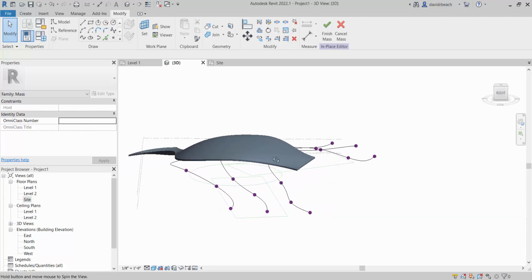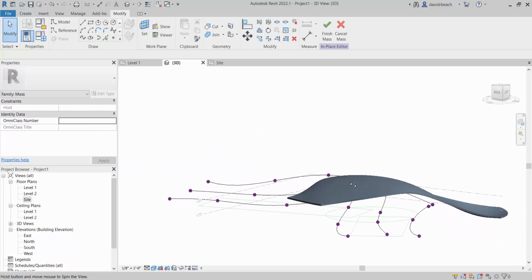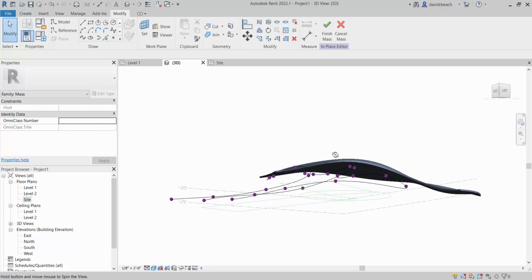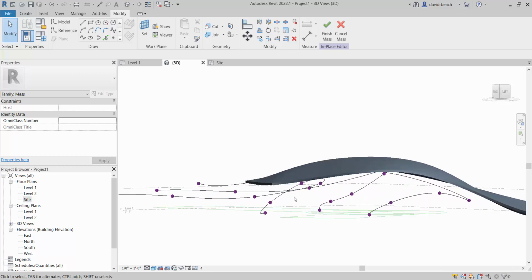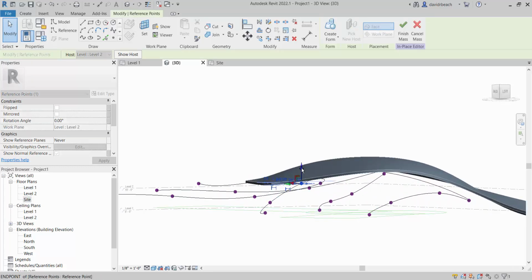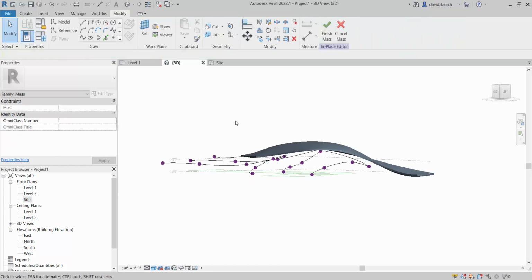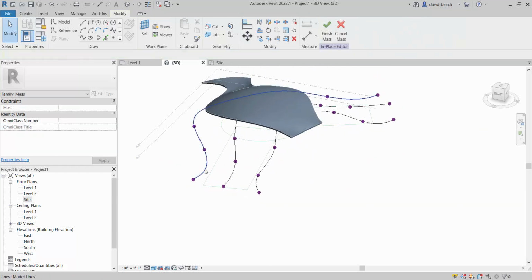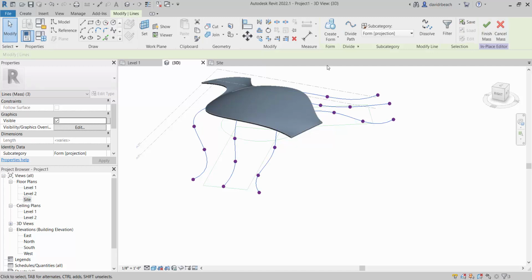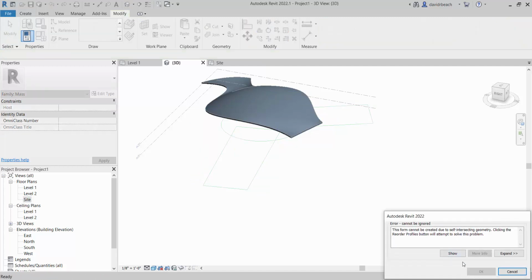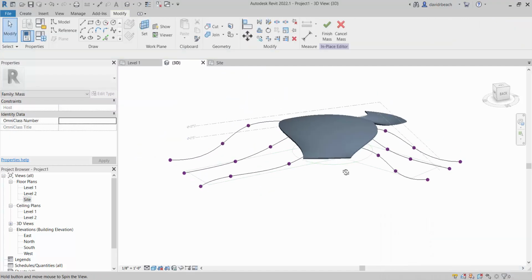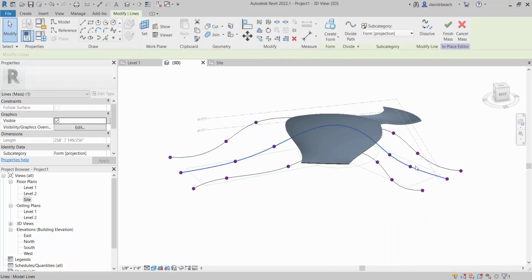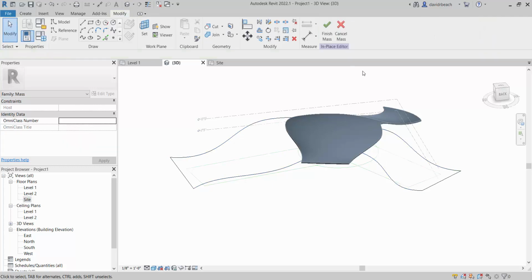There might be a method inside of Revit that lets you control what is attached to what first. But to be clear, I'm not sure how to get to that option. So we're just going to delete. Let's rebuild, and let's see if that makes a more rational form. Still having that issue. Wow. So let's look at one other method. Let's delete that spline, select those 2 points, and let's create it.